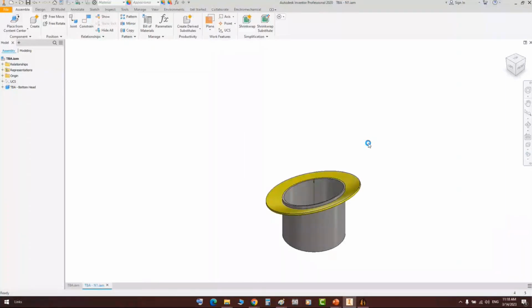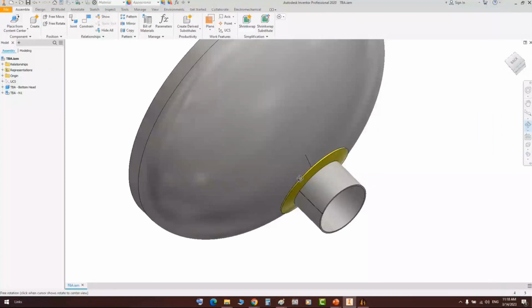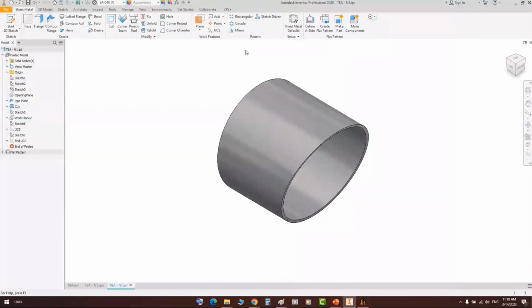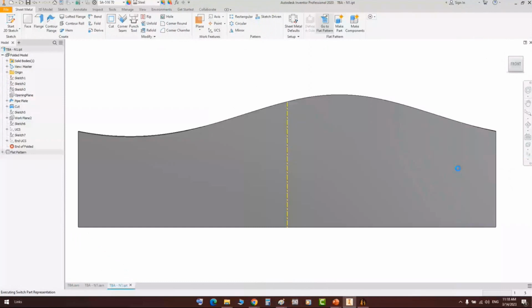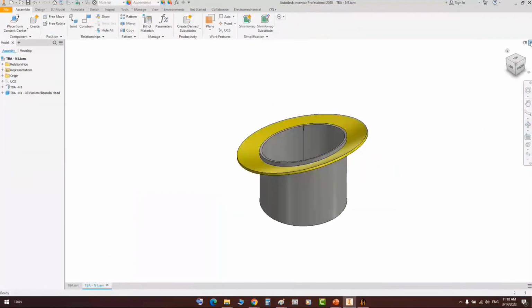Here we have this nozzle made from blade, and you can see that you have a longitudinal welding line. If you open this nozzle and open this part, which is this shell part, when you create sheet metal development, you will get this contour of the nozzle connected to the shell. Let's close this for the assembly and come back here.